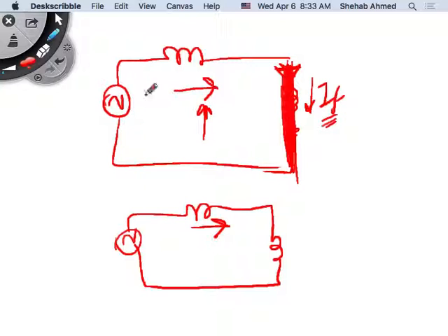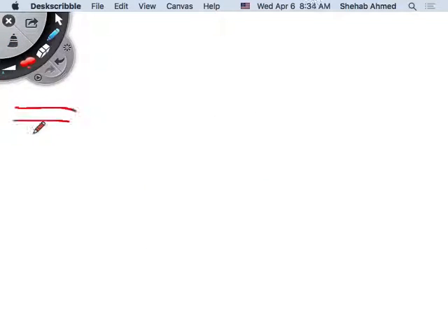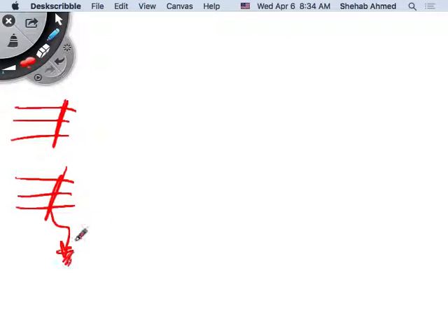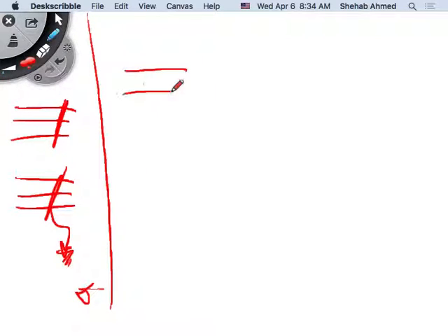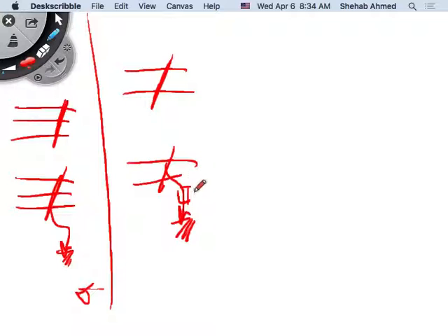That is only one of the types of faults that we cover, right? Three phases shorted, or three phases shorted and connected to ground. This is the only type of balanced fault there is. The other types of faults that we talked about were two phases shorted, or two phases shorted and then connected to ground through an impedance or without. If without an impedance, it's called a bolted short circuit. If it's with an impedance, it's a fault through an impedance. We just call it that. And then the other type is the single-phase-to-ground fault.